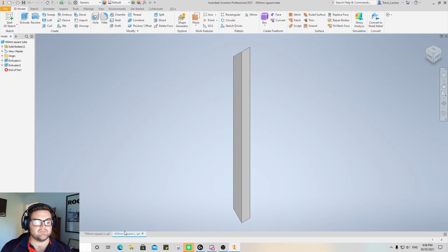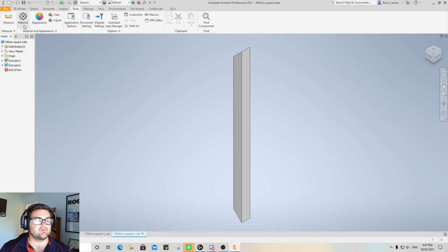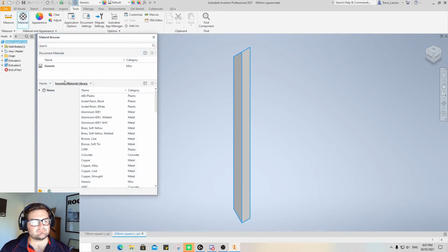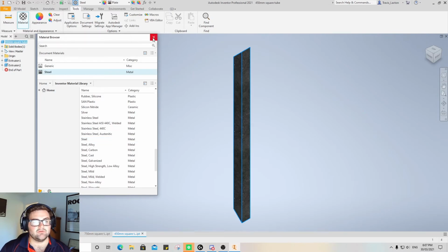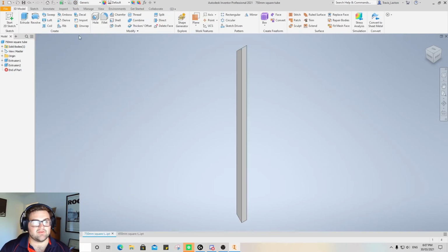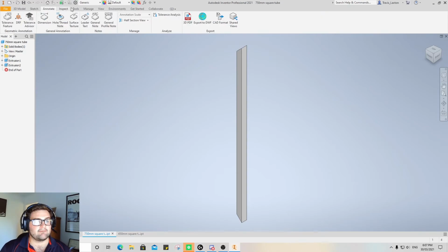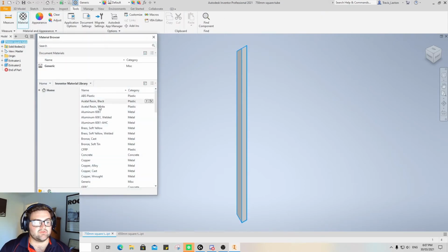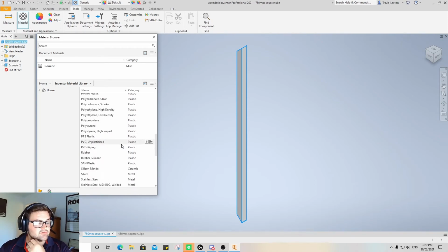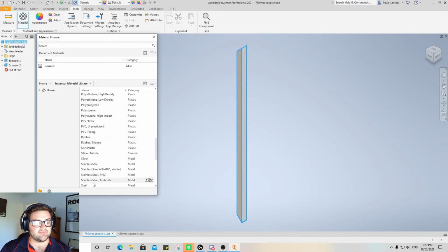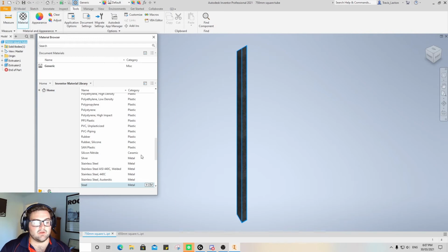And then finally, what I'm going to do, make sure I select mild steel or steel for these. So if I go to tools, material, and then I'm going to go down to steel, and we're going to assign that to selected. Same with this one, tools, materials. So this way we've made our different materials, we've identified within this that they are the right material. There we go.